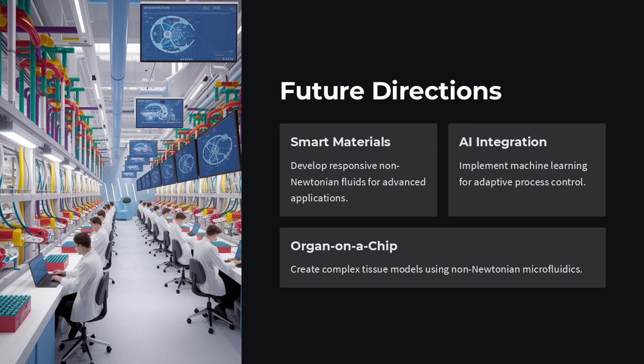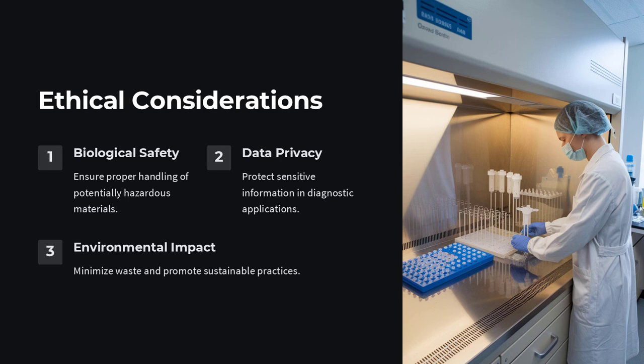In conclusion, the behavior of non-Newtonian fluids in droplet-based microfluidic systems presents a rich tapestry of challenges and opportunities. Their unique rheological properties, whether shear-thinning, shear-thickening, or viscoelastic, profoundly influence droplet dynamics and encapsulation efficiency. By carefully tailoring flow rates, channel geometries, surfactant concentrations, and polymer compositions, engineers can optimize droplet formation to achieve uniform size, high frequency, and robust encapsulation.